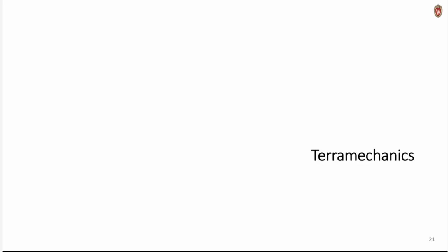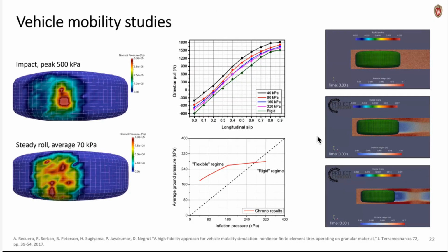So I just wanted to tell you a little bit about what capabilities we have in terms of terrain mechanics in Chrono. I am not going to talk much about what you can do with this, except for this slide. If you do have the capability of modeling deformable terrain, then you can do all sorts of interesting analyses, like looking at the distribution of pressures in the contact patch of tires, or looking at different performance metrics of a vehicle, like the drawbar pull, looking at the relative importance of internal tire pressure and internal stresses in the deformable terrain, or look at the effects of multipass, right?